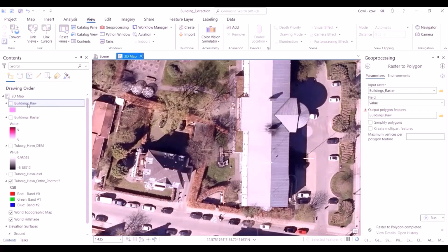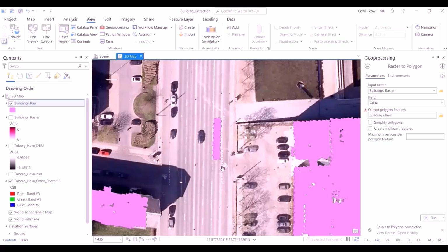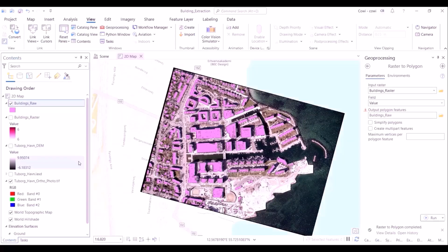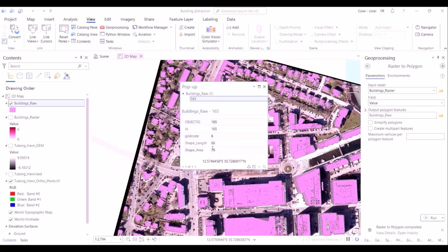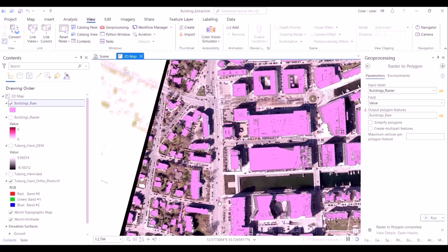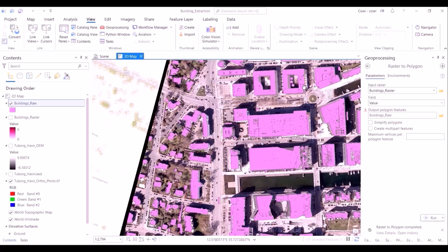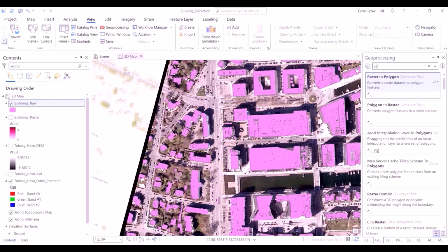How do we basically perform these corrective actions? So at first, let's say we want to remove certain features such as the one on the road, which is clearly not a building. And how do we basically remove that? It is a very simple technique. We examine the dimensions of the buildings. We see that they have a particular length, they have a particular area on an average, and certain features which are different, where the length of the particular object is below a particular standard or the area is below a particular value.